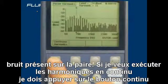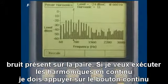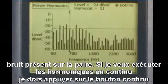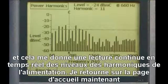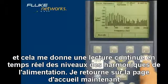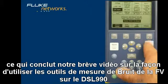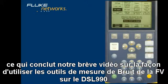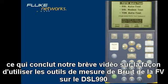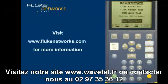If I want to run the harmonics continuously, I'd hit the continuous button. And now it gives me a continuous reading in real time of the power harmonic levels. Okay, I'm going to back out now. And that concludes our brief video of how to use the VF noise measurement tools on the Copper Pro.